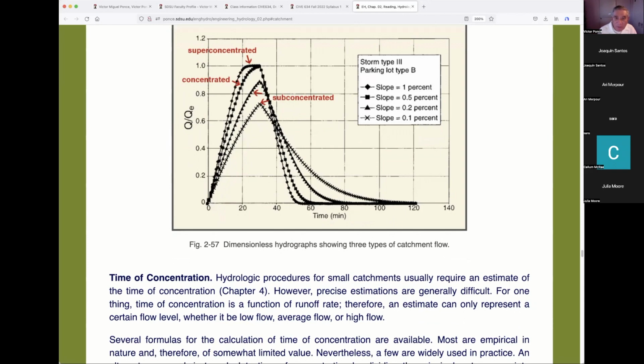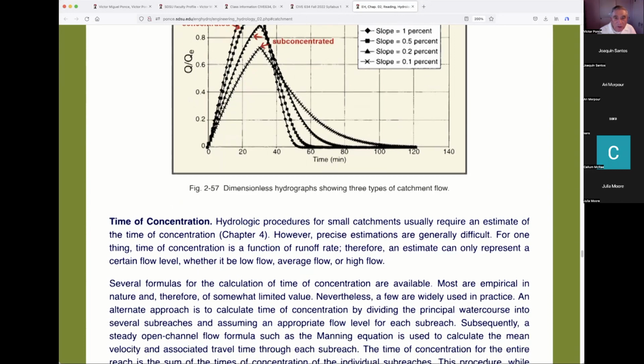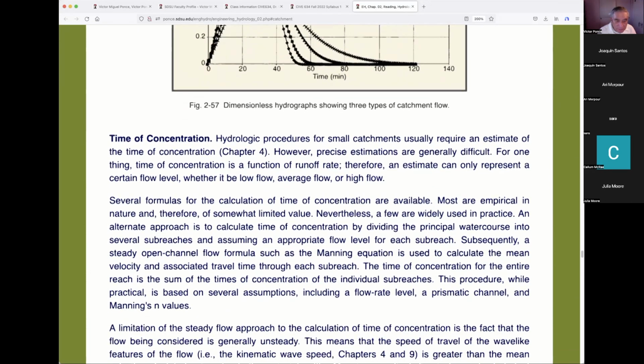What does grid independence mean? I know that those of you who took computational hydraulics last year have heard me talk about it. Grid independence refers to the property of a model not to change its results if you change the grid. Many models do that, which means they are not completely controlled by the numerics.